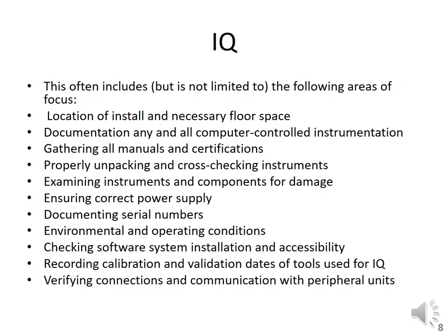Gathering all manuals and certifications. Now, before starting the installation and during installation, you must be aware of any manuals or certifications which are being provided by the manufacturers or the company or the vendor providing the machine. Any manuals, any certifications which are relevant to the machine, the equipment, you must have all of those, you must gather them all, and you must keep them in a proper way, right? Properly unpacking and cross-checking the instrument. This is important.